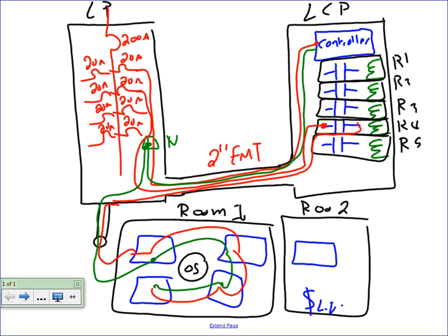That's what you did when you circuited the receptacles, power the lights. When you power the light, that's what you did, power them. Assign a circuit for them. And which relay do you think is going to control this circuit, this room now? Relay number 4. Relay number 4.